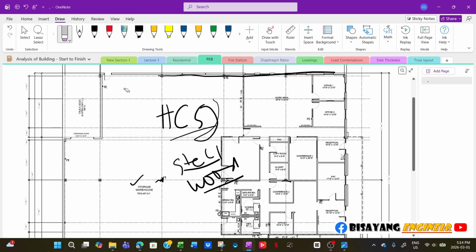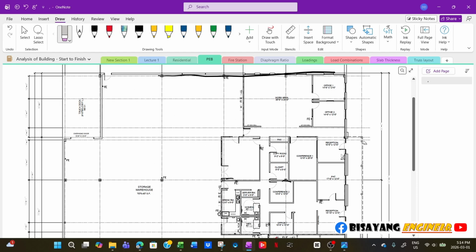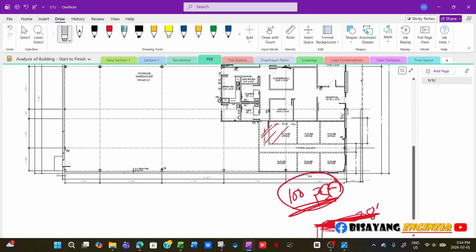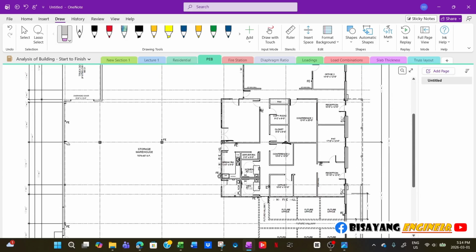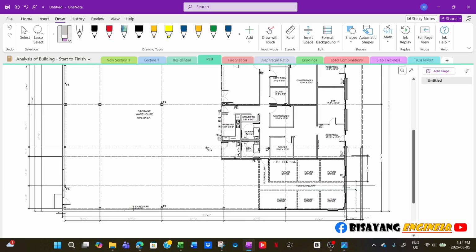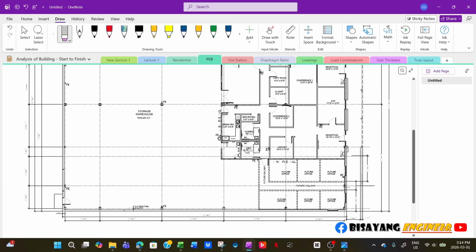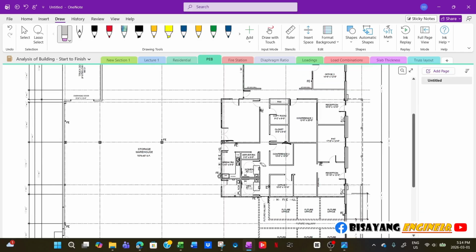now if you notice, we have interior columns, because this is really a big building. So usually what we do here is, if there are none specified, like column locations here, you can talk to the architect that we need columns along this grid line to cut the slope.